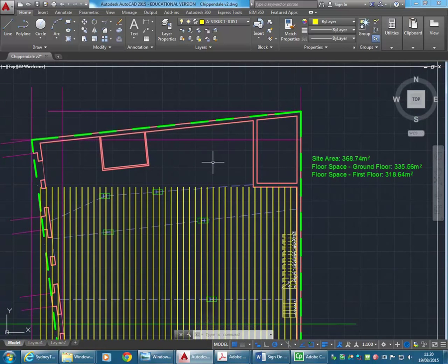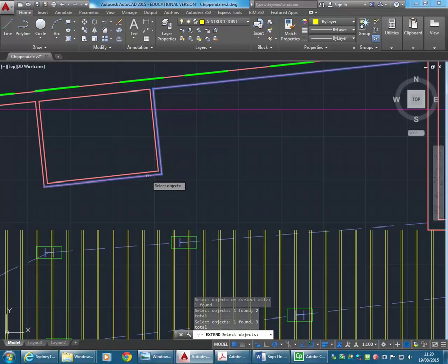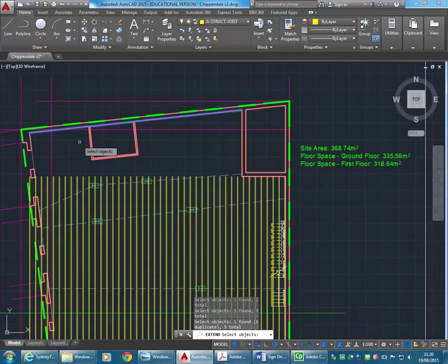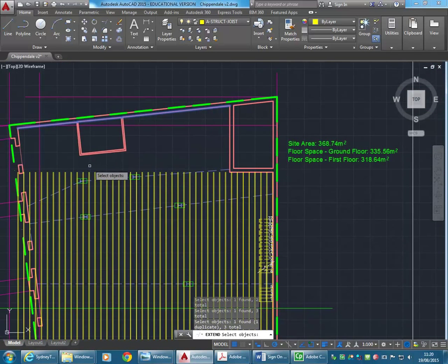And so here, this is again where AutoCAD is far more powerful than Revit for drafting. You can just use extend and choose the wall lines up here. Well, actually, sorry, it goes over these, so I won't select these, but I'll select just the ones at the top. I'm assuming the joists would have to go over that.